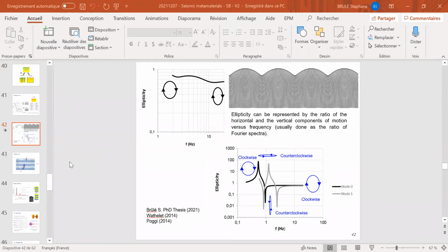Transforming a homogeneous to a two-layer model, we introduce the dispersion wave. The dispersion wave is also interesting because for some very specific frequency, we attenuate the horizontal displacement, and the vertical one is dominant. Vertical dominance is much less deleterious than the horizontal displacement.